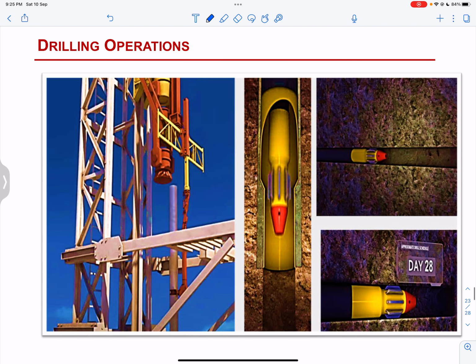A few hundred feet above the target shale, the drilling assembly comes to a stop. The entire string is retracted to the surface to adjust the drilling assembly and install a special drilling tool. This tool allows the drill bit to gradually turn until a horizontal plane is reached. The remainder of the well is drilled in this horizontal plane.